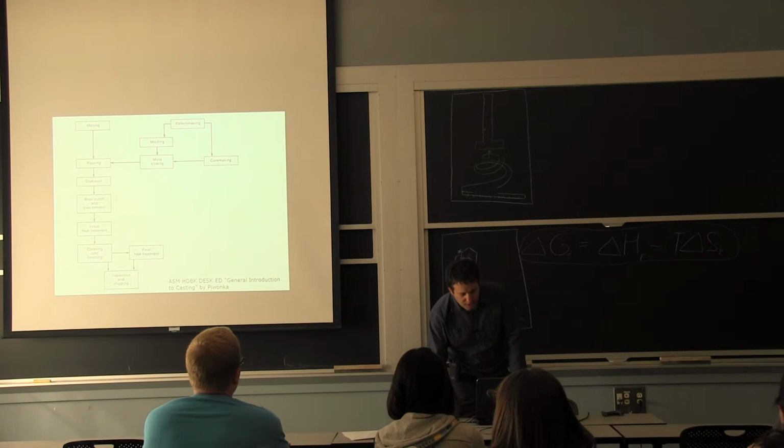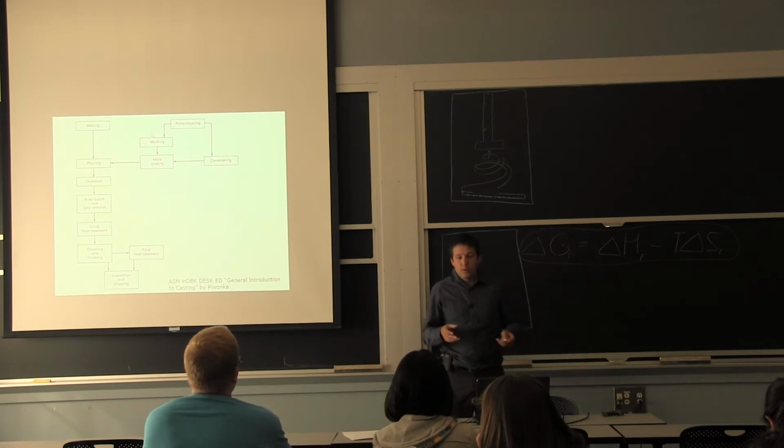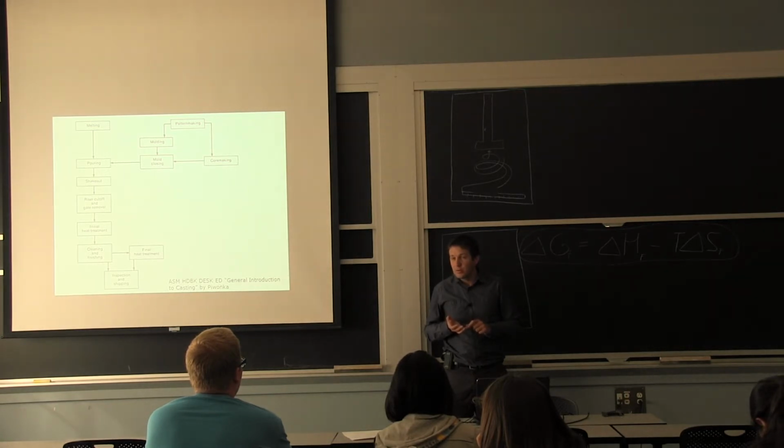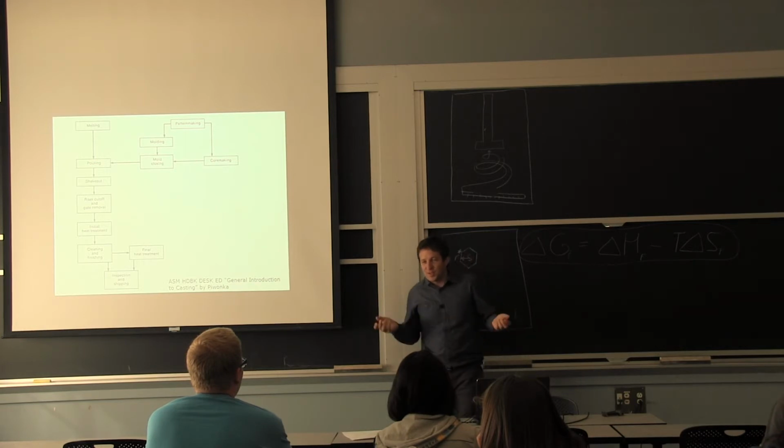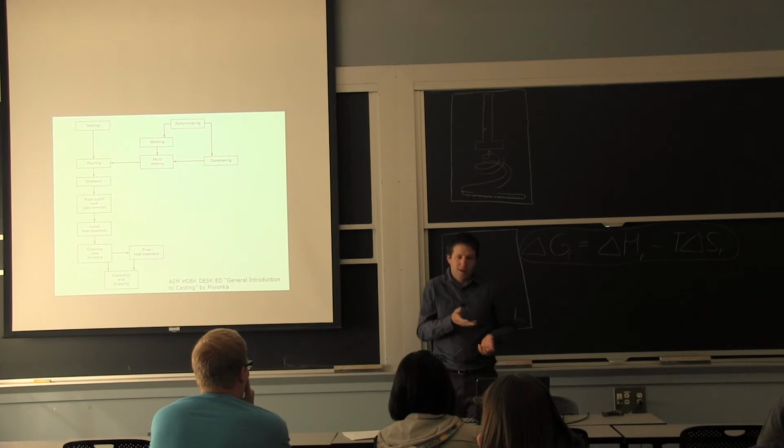But I'm bringing it up here because, as part of our review, we essentially concluded that, first of all, making molds for platinum is not easy because it melts at a high temperature. So you need a mold that can resist higher temperature than most other metals that we cast. I mean, one of the easiest is aluminum. It's relatively lower temperature. You can use permanent molds, but at those temperature ranges, you almost have to go